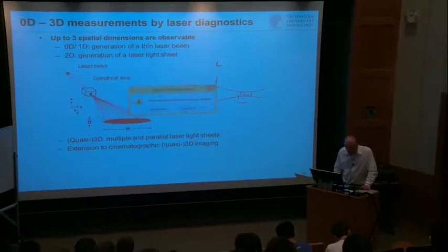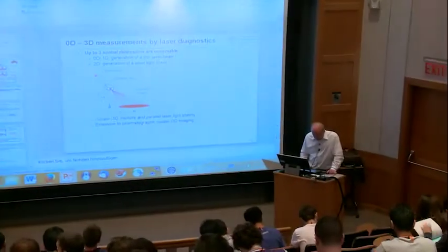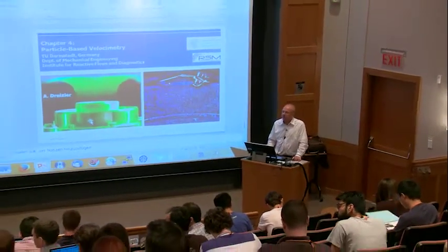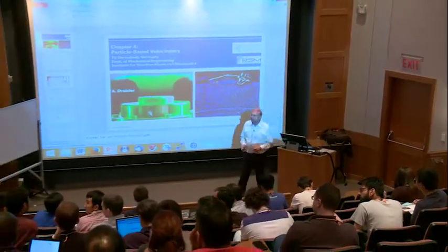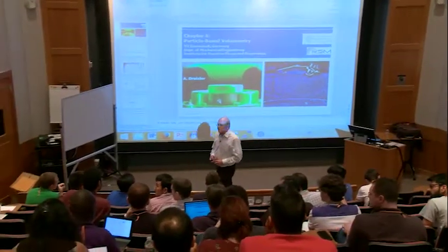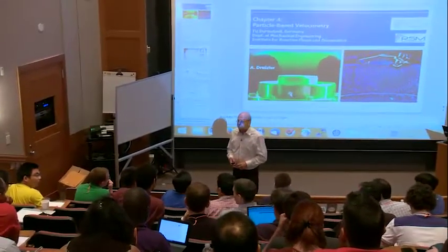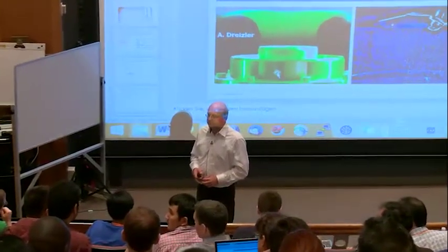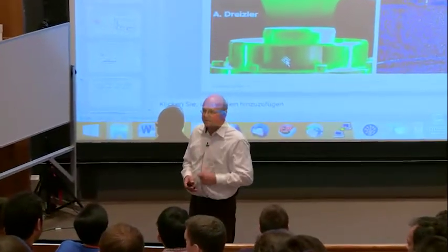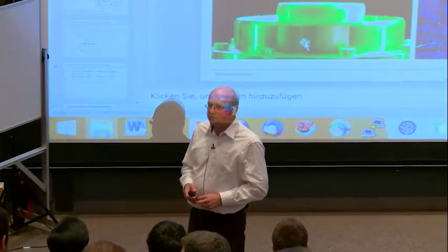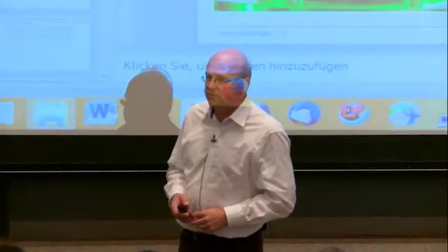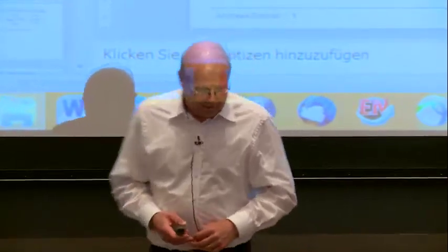Unless you have any questions. Yes, please. In order to estimate whether we are sufficiently resolved in space and time, we compare our results regarding the Kolmogorov frequency and Kolmogorov scale, right? Yes. But in non-reacting flow there is no problem. If you have a reacting flow, the estimation of the kinematic viscosity depends on temperature, and since the heat release changes the density... Exactly. Yes. So how do you want to compute that?